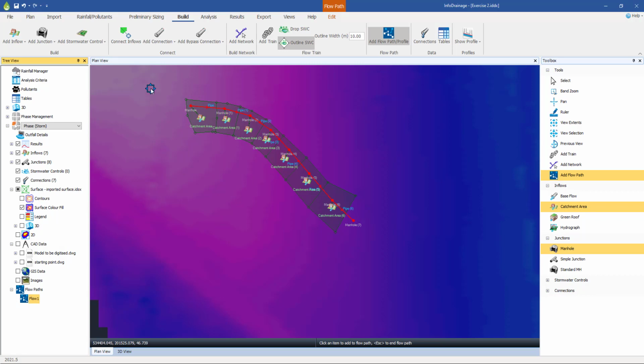And the pipe design is conducted in accordance with UK standards, so that's the DCG, Design and Construction Guidance, which followed on from the old SuDS for adoption, the different stages of that. And that design guidance in particular sets out pipe design as a two-stage process. And it is important to recognise that there are two very separate stages to this.